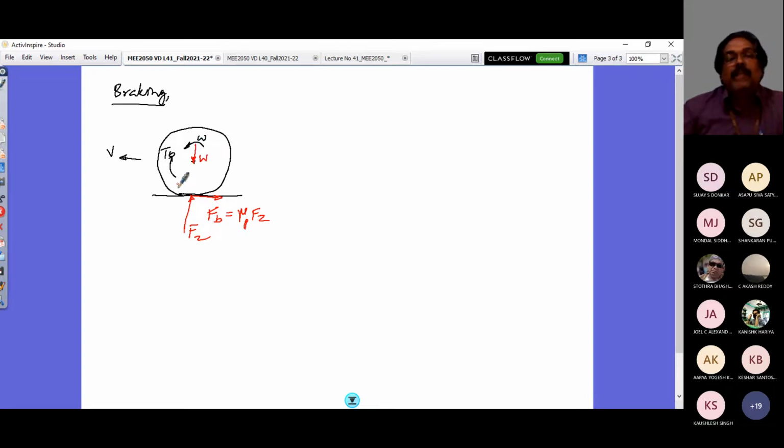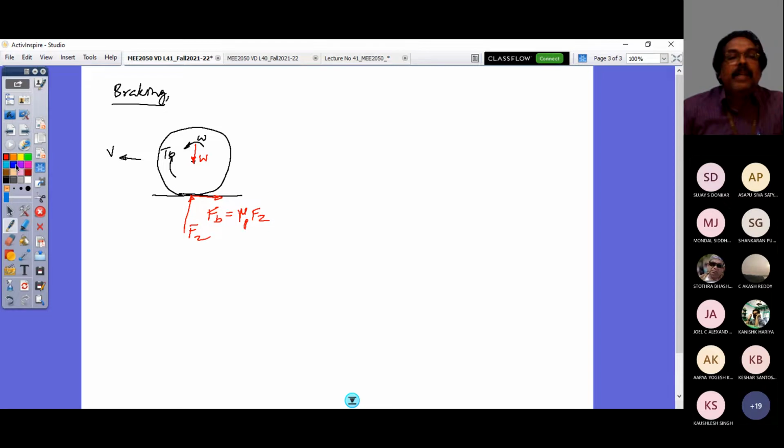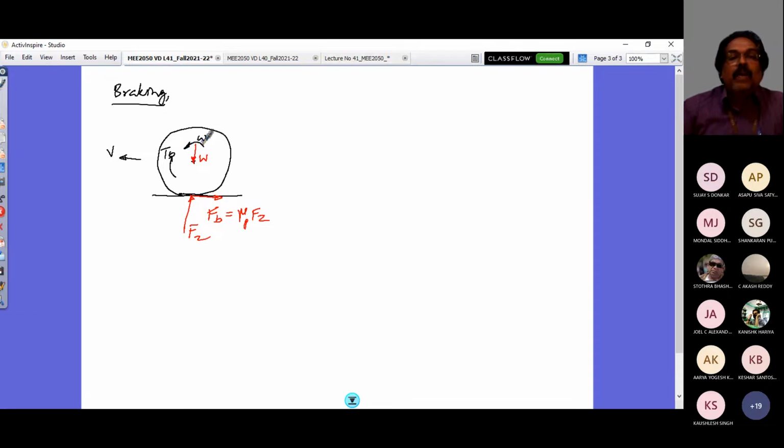Here I have Fz, which is normal, because of the load that is acting on the wheel. So this is its free body diagram. It's not only that. What is additionally there is the kinematic parameter. If you look at this omega, because of this it would start decreasing. If this starts decreasing, what does that mean? Your omega dot would be happening. So omega dot would be deceleration in the opposite direction. You would see that this FB would facilitate a moment at the wheel center. That moment we call the tire torque, and that would be FB into R, the radius of this wheel. So FBR.